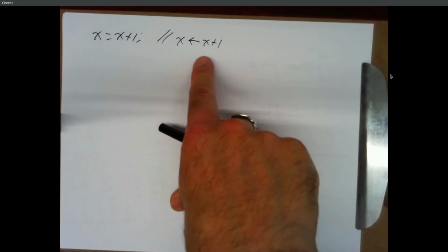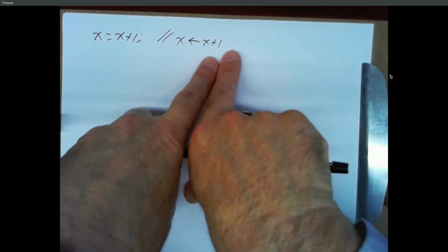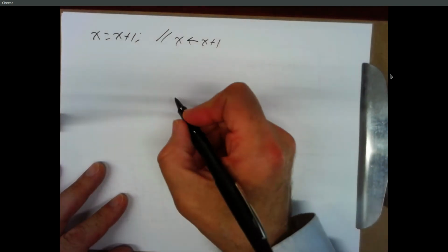So in some languages, you write it like this. You say take x, add 1, and store that back into x. Okay, so it's a read, modify, write. Let's see if we wanted to build hardware that could perform this function, that could take x, add 1 to it, and store it back into x. Well, we've got all the pieces. So let's suppose x is a 4-bit number, so 0 to 15, or maybe -8 to 7 if it's 2's complement. But it's a 4-bit number,